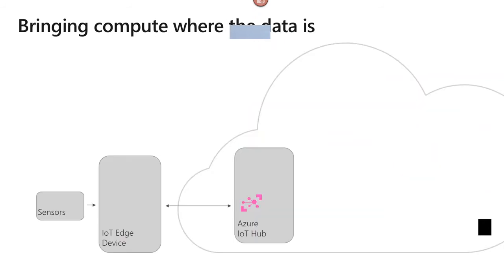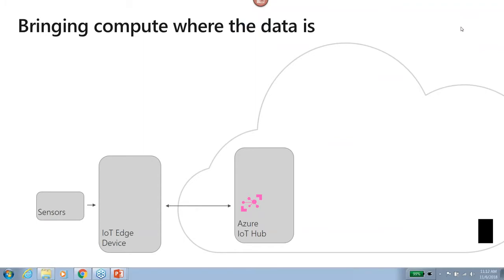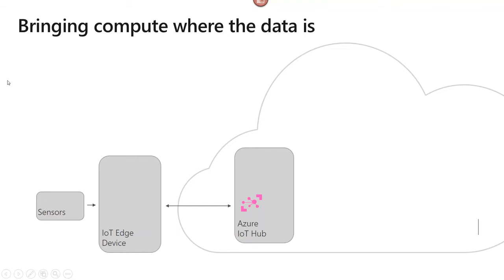So let's start here. You have a device collecting data from a machine. Maybe it's that oil well. Maybe in this example, that oil well also needs some protocol translation, right? Maybe this is an oil well that only understands a protocol like Modbus. Maybe this is an intelligent building that understands only BACnet. In any case, you need to translate that information into something more modern. You're going to take that information and monitor it in a machine model that you create, or maybe one of your partners create, and then you're going to take action on it like we talked about earlier.